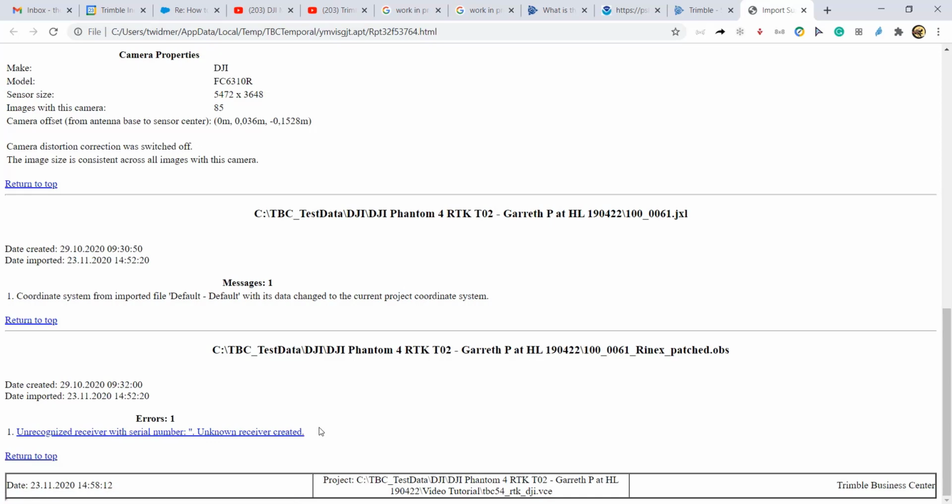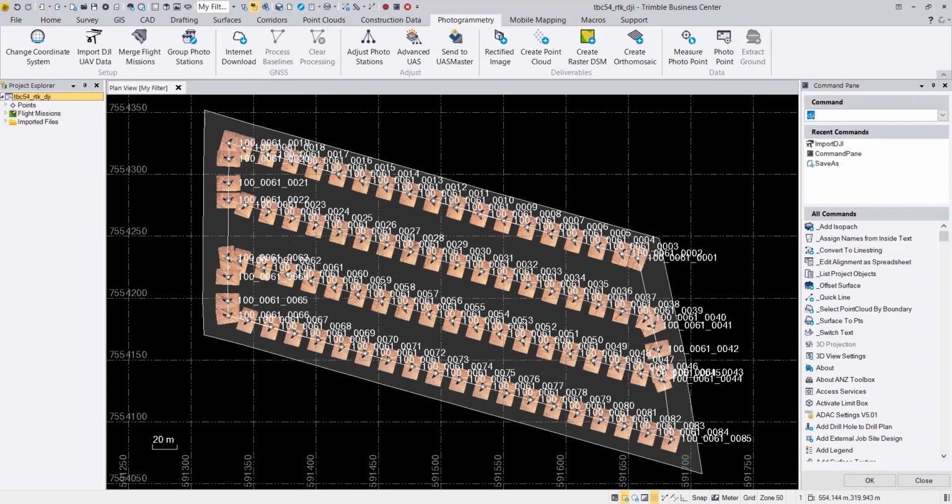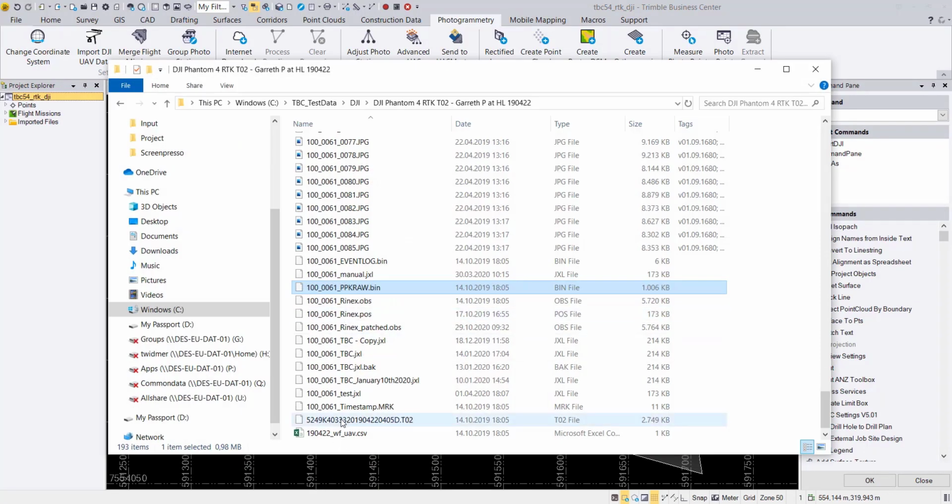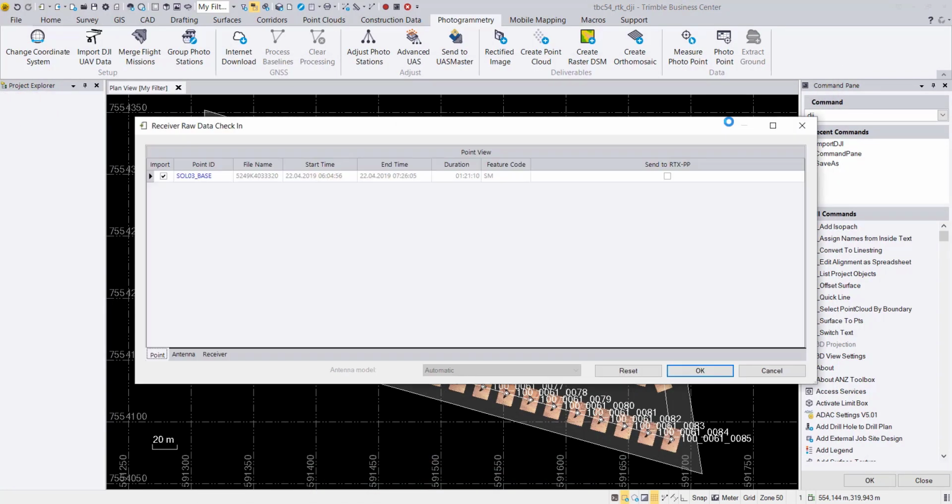And this will, as I assume, then be solved, because then our receiver will be the data in the T02 file, and then we can use this one for our current further processing. Okay, next step is then drag and drop our T02 file into the project. So we just take the file and move it into TBC, and then this data is imported. And also here we don't need to do any changes, everything is set automatically correct, so we will not make changes here.